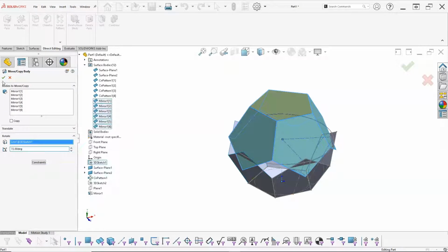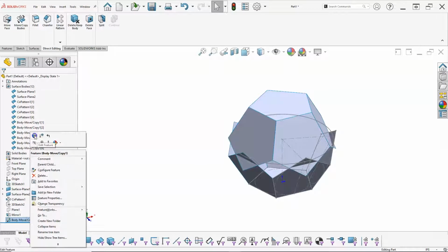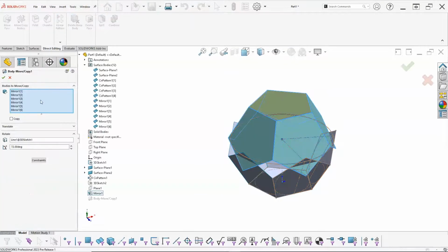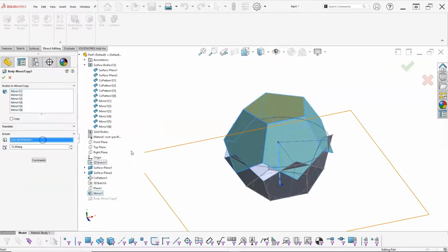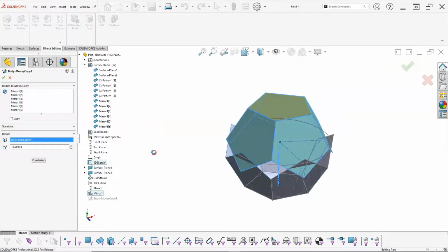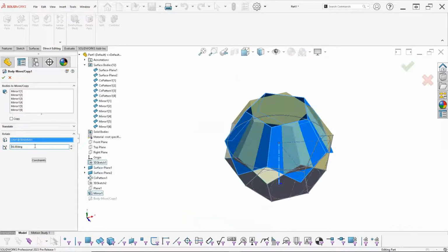And when I was doing that sketch, I in the process decided that I didn't really need that. So let's go ahead and see what we get. And that did not rotate. So what did I tell it? Okay, those are the bodies. And that is the rotation. Oh, not 72 degrees. That is one complete segment. How about 72 divided by 2? There we go, doing math again.